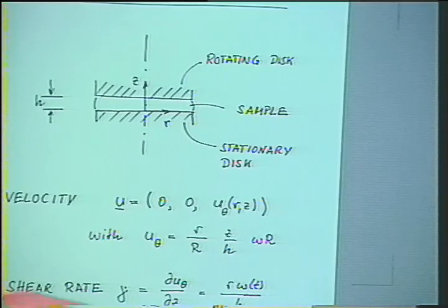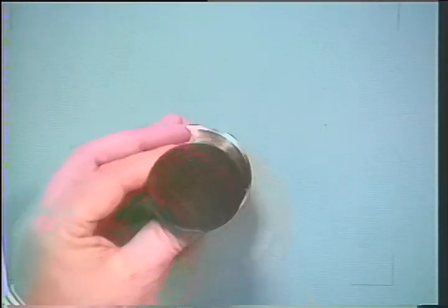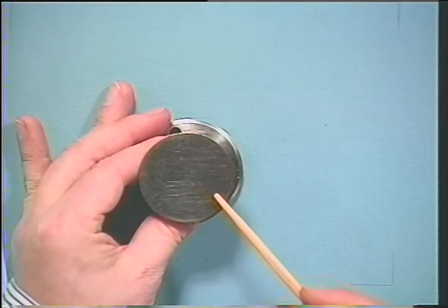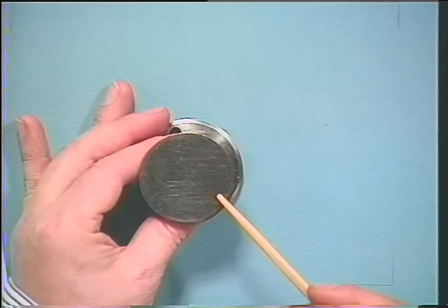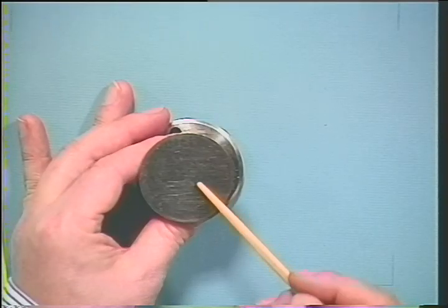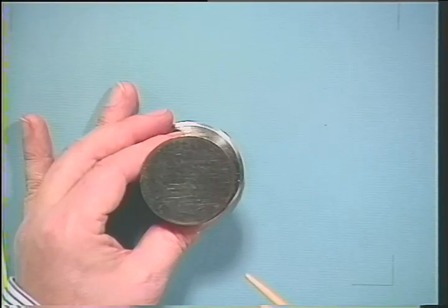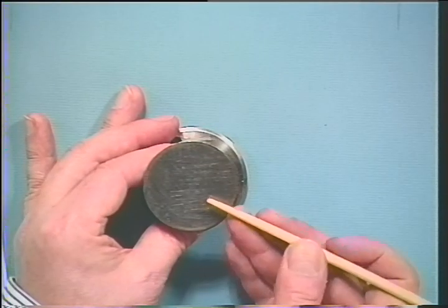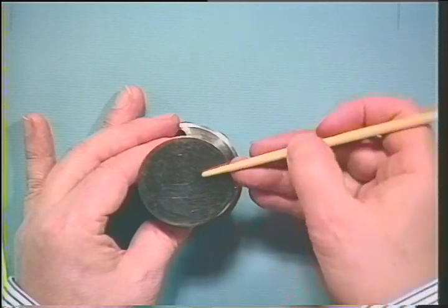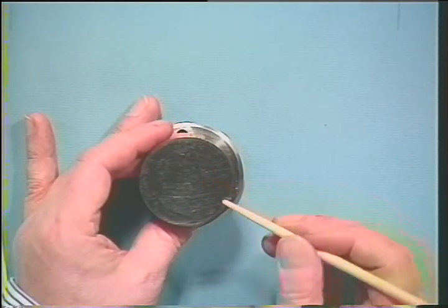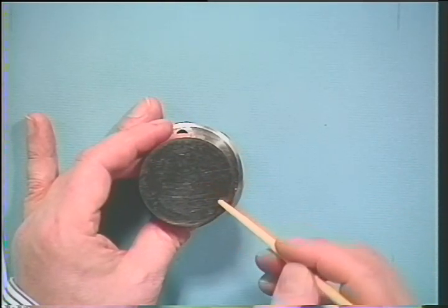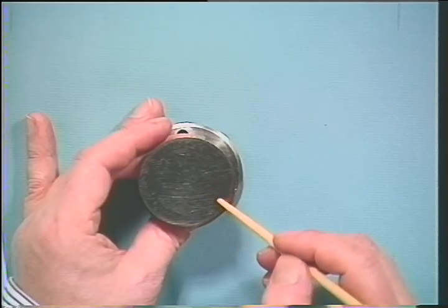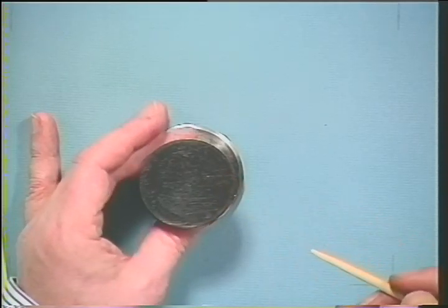And if you would take this type of fixture and draw a large line in here, the outer edge of that line would move at a different velocity than the inner point of this line. In this case, it would actually stay radial, because it would accommodate the shorter path at the inner, shorter radius, and also the longer path at the outside. So that's what we are going to look at now for a specific material element.